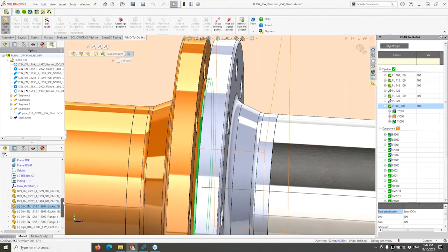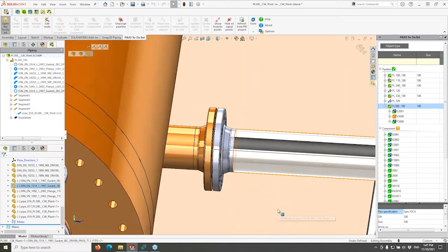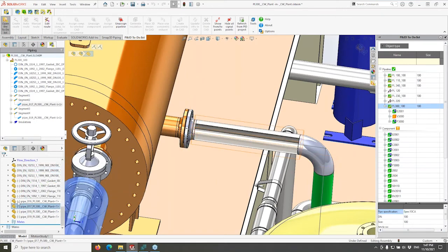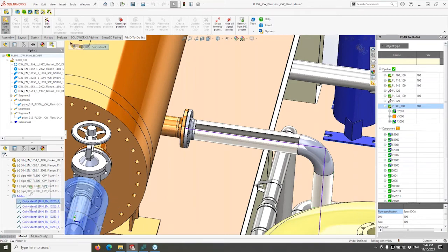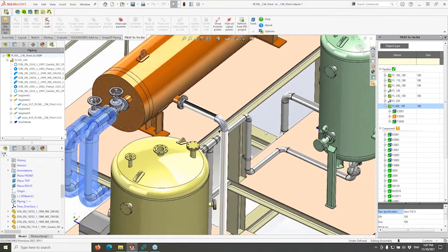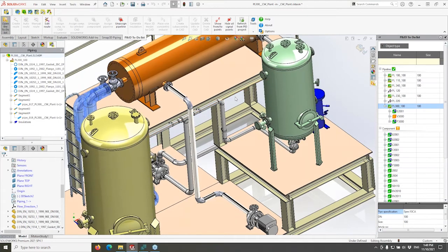And now if I come back over here and look at my SOLIDWORKS feature tree, we'll see that we have all of these part files now inside of here. We have all of our mates, all of our pieces of pipe, and it's created all of these standard SOLIDWORKS mates in here, coincident, things of that nature. So what does that mean? And why is that important? Because with this pipeline and all of this piping that I'm doing with SMAP, I can still share this data with anybody that has a license of SOLIDWORKS or eDrawings for that matter, since it's a viewer for SOLIDWORKS models.